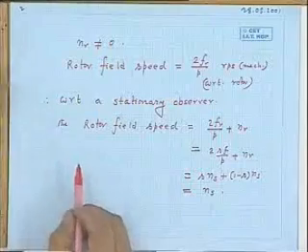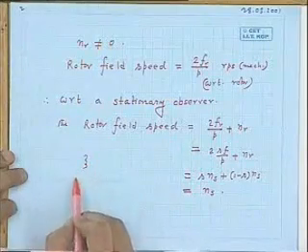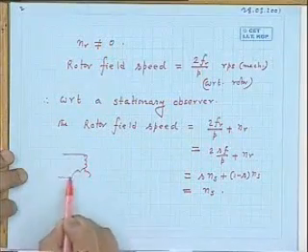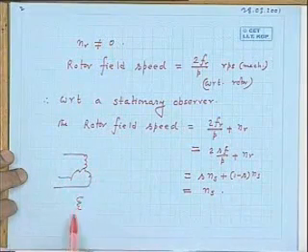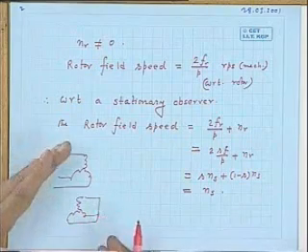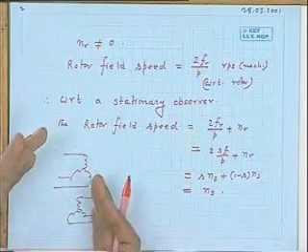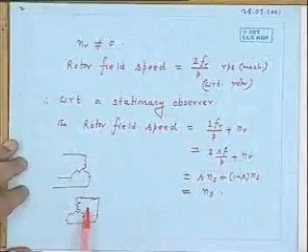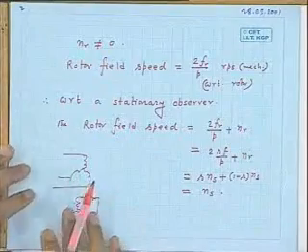Therefore, what I am trying to tell is that the stator winding of the machine has to react whenever there is a rotor current, because it has something to fulfill: voltage balance in the primary circuit is to be maintained by KVL. So whether the rotor is running or not, when the rotor circuit is closed, the stator really cannot distinguish it.